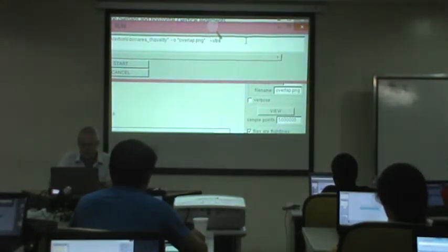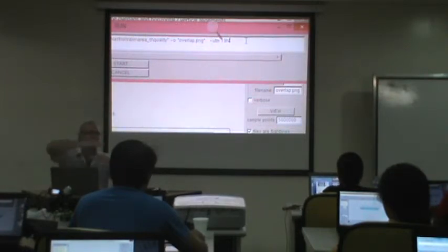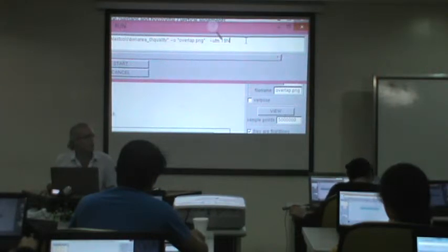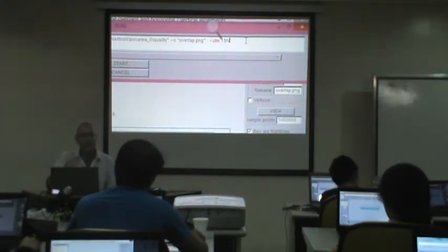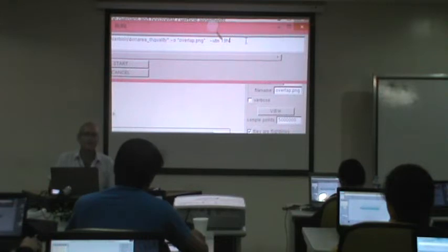Minus UTM space 90 N. N doesn't mean north. N means everything N, O, P, Q, R. There's some kind of letter code for the UTM zones. Everything N and higher is northern zone, including S, and everything M and lower is southern part of the hemisphere.